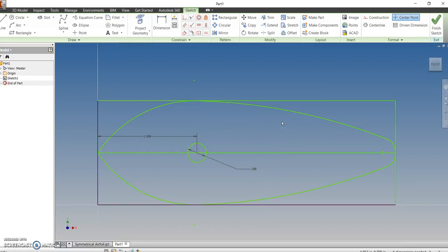And then the next thing after creating that circle is you're going to want to delete all these unwanted lines that we have in here. Basically these construction lines, some of these dimensions and things, we can take those out. I can just select those with my selection cursor. Again, I have no tool selected right now. If I just press escape, to make sure I have no tool selected, I'll then select the dimensions and press delete. With some of these line segments I want to take out, I can use what's called my trim tool. It's under modify in my modify panel, and I'll take those out of there. Delete all these items.